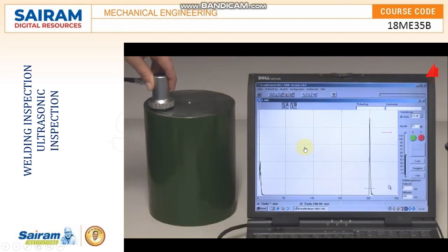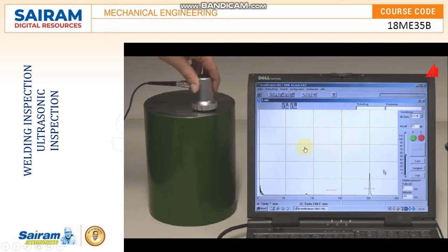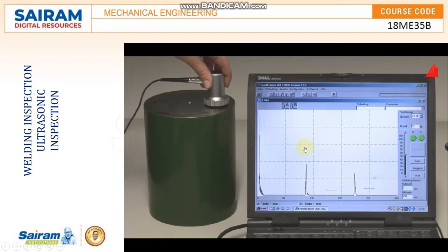The material tester scans the upper front end of the cylinder with a probe and observes the monitor. A defect echo appears on the monitor. This defect is located in a depth of 130 millimeters below the surface. Another echo indicates a defect in a depth of 87 millimeters. The second smaller echo at 174 millimeters is caused by double reflection on the same imperfection.